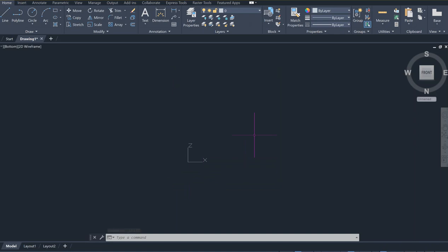Second, limits is a very big deal, and we go to the limits command by simply typing limits. I'm used to typing the English names of the commands, because I've been using AutoCAD almost from the beginning. Limits is a rectangle, and you define it by XYZ coordinates, particularly its lower left-hand corner. Traditionally I accept 0, 0, enter, and for the upper right-hand corner, if it's bigger than 6 inches, I will take it.